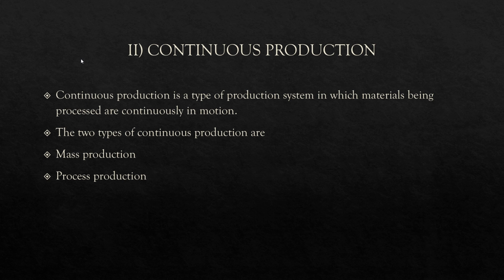I will give you a great example for this continuous production. Cement manufacturing. It's a continuous process. The raw material for cement is limestone and clay, and these two are first of all cleansed and all the impurities are removed, and then it is ground. Then it is blended with iron ore. Then the next process is heating in kilns, and the heated product, that is a burnt product, is ground to cement, and this cement is packed and stored, and later it is transported for distribution.